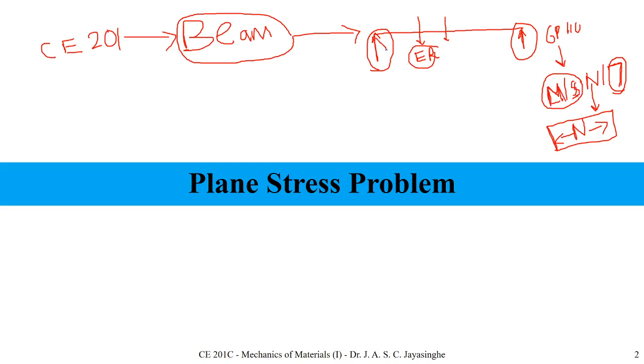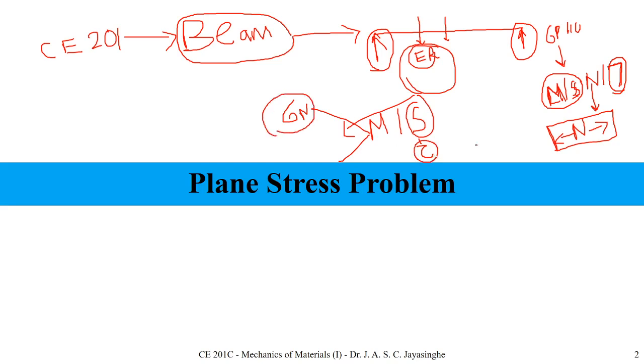First we understand the external forces and find them, and after that we develop the bending moment and shear force diagrams for the target beam arrangement. What we realize is that due to the bending moment and shear force, we can see stresses. Due to bending moment we see the normal stresses. Due to shear force we see the tau component, the shear stress component. In the last few lectures we tried to understand the variation of these two stresses across the beam cross section.